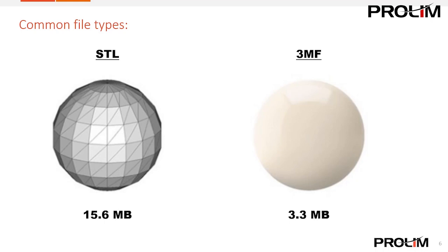The 3MF file type, 3D Manufacturing Format, is an XML-based open-source format designed specifically for the additive manufacturing process. This file type includes mesh, material, color, and texture, all directly from the model geometry and contained in one model file. The 3MF file size is dramatically smaller than an STL format as well. Ideal for more complex, detailed 3D prints and large files.